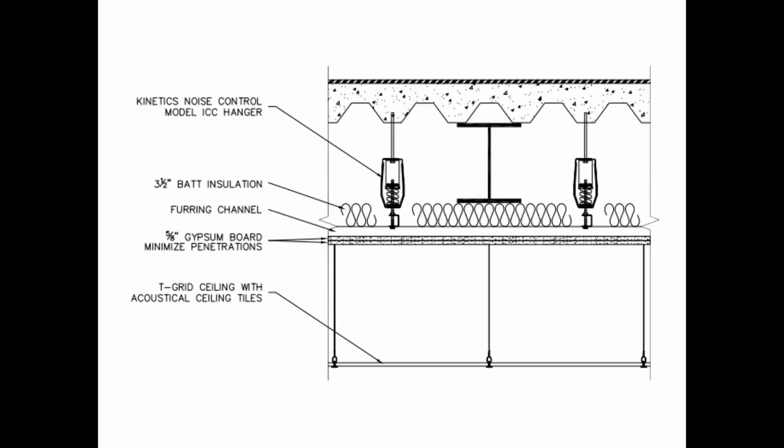You can mix and match those to whatever amount of diffusion and or sound absorption that you need. So having this sound isolation ceiling and then an acoustical ceiling down below, and also you might be hiding stuff in here. Like you want to minimize the penetrations through this. So if you have ductwork or some sprinklers or something like that, you can run through there, that allows you to hide them.